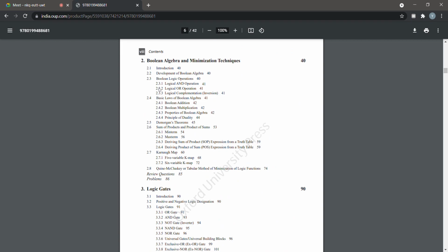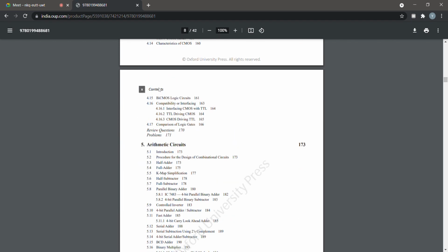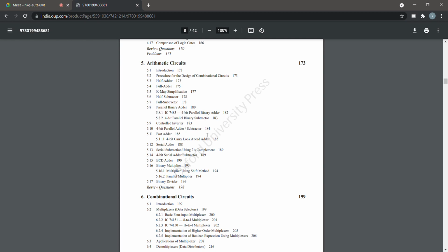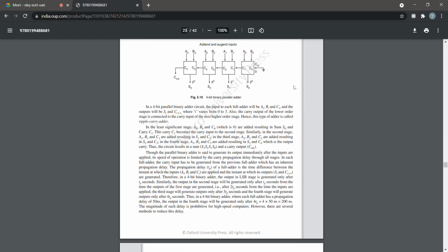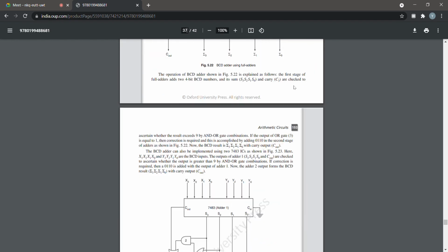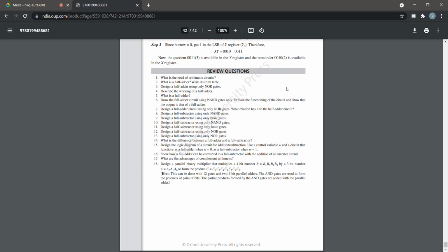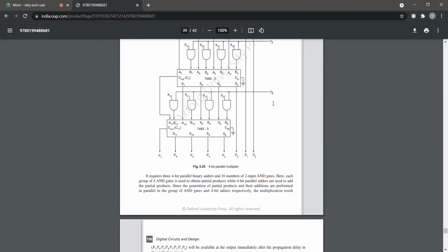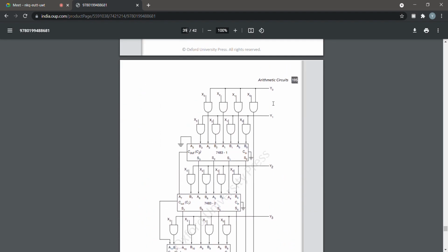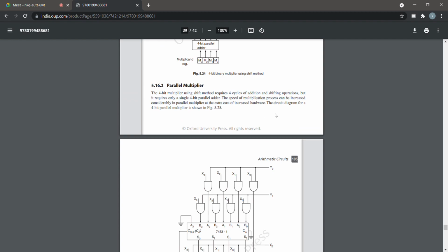So think about the last partial product. After accumulating that, it can grow up to 7-bit possibly, or 6-bit. Even if it is 7-bit, it will come up to this point, right? It cannot go beyond this. So once again, can I manage with another 7483? Because I need to add only these 4 bits with this much only, because the other portion of this partial product, which is nothing but 3 zeros, will be added to that. So in that case those 3 won't change, right? So here also probably I can manage with a single 7483.